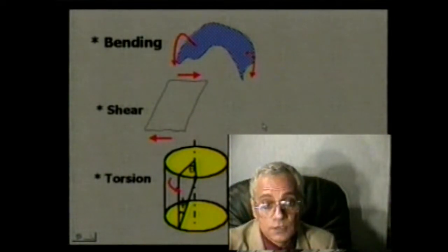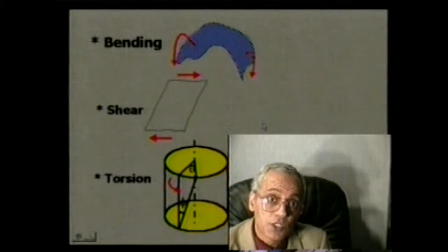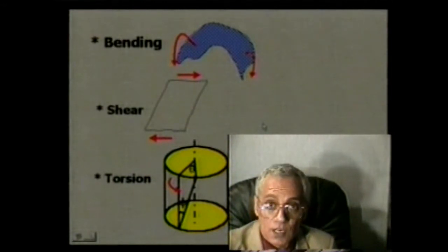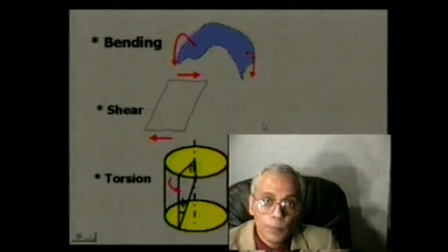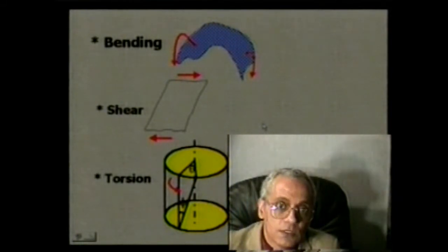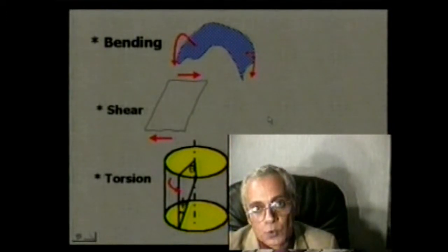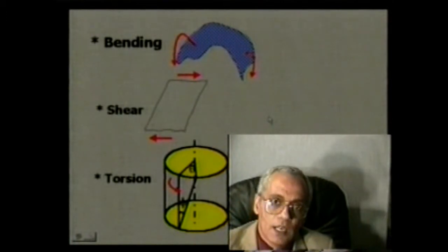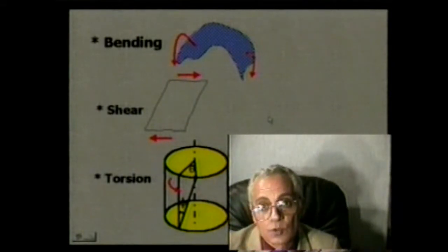You take the yarn and look at the weaving preparation, and you will see the tremendous stresses of various modes that the yarn is subject to, all the way to the weaving process. To me, the loom or the weaving mechanism is the best demonstration of multiple stress modes, where the yarn is stretched, bent, compressed, and rubbed against different parts of the loom.